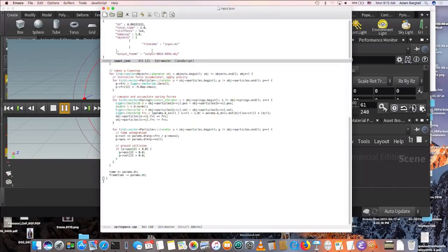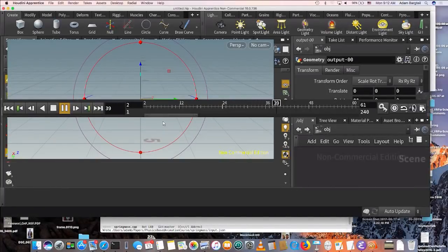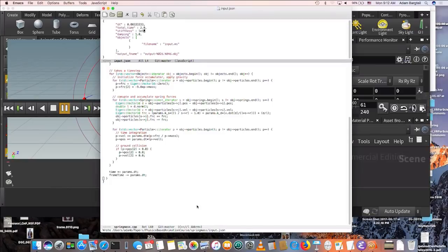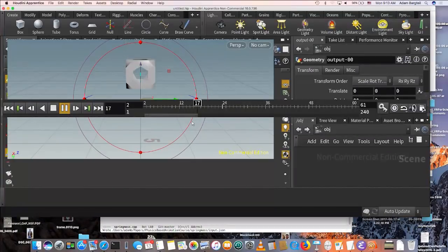We can go back to our code and change the stiffness, make it a stiffer material. And if we do that and run again, the system actually blows up. We had too large a stiffness for the time step we were taking, and you can see in this first frame that it goes unstable. And we'll be talking later about what all that means when we talk about implicit integration. So we'll reduce the time step, and that'll make things more stable. And now we'll run again, and we're stable, but we're a more stiff system. And you can see we bounce a little higher.